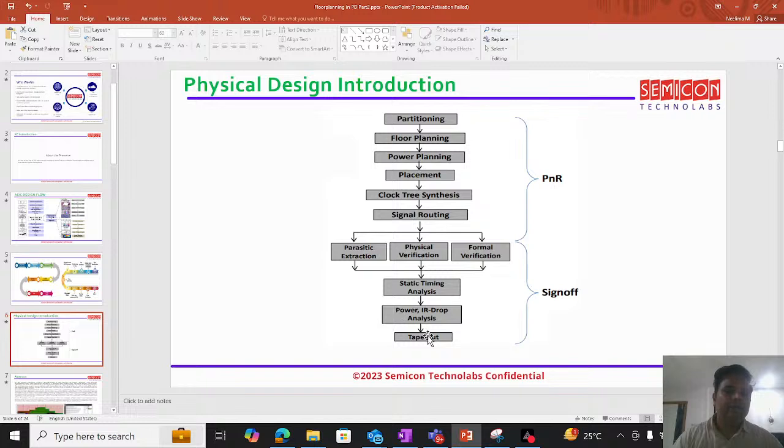Okay, and then finally tape out. Of course, before going to tape out, we have a lot of things to take care of, right? I mean, we need to make sure that our checklist is proper, and correct by construction has happened, reviews are happening, jiras are closed, we are aligned with the customer on the exceptions we are applying for the design, right? So many things go in place, and finally we move the database to tape out.